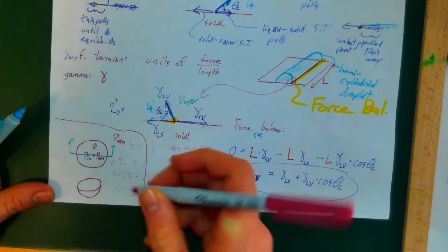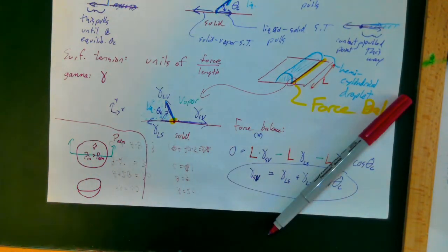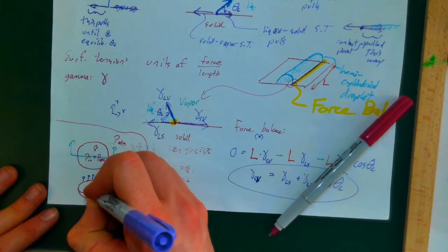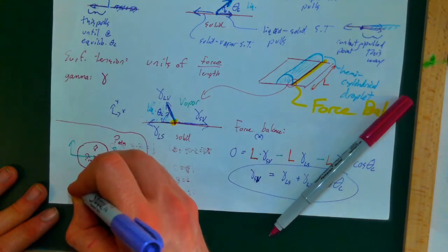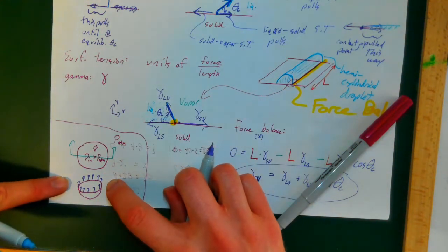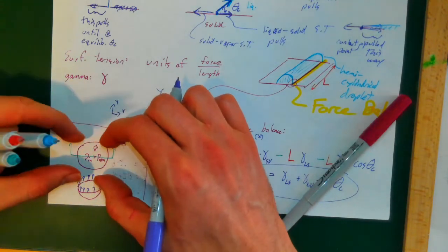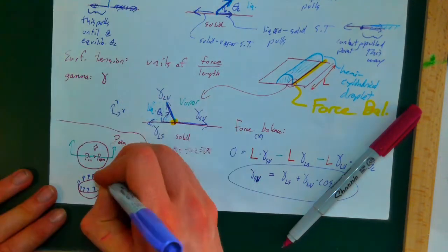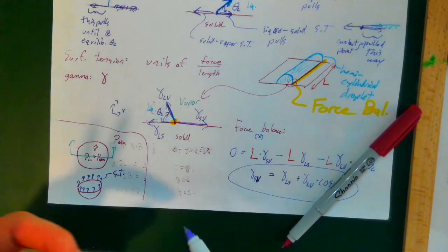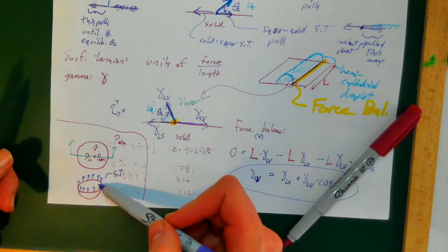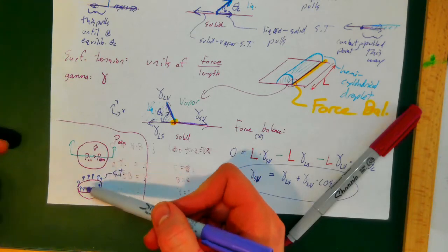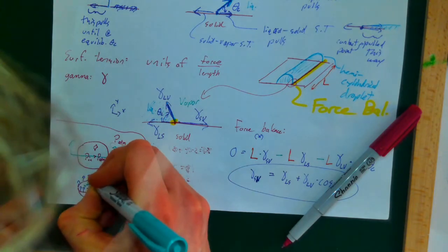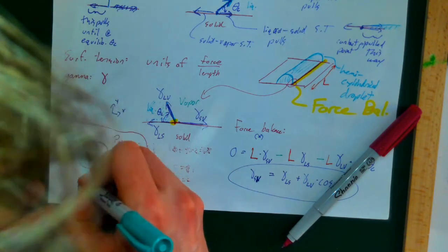imagine a hemispherical half of a bubble. The liquid vapor surface tension of this droplet is essentially pulling along the equator of this, it's basically trying to pull the two halves of that surface together. So surface tension is basically pulling like this. So what does that mean? Well, if I were to imagine, there's no net force on this bubble, right? It's not going anywhere. So what does that mean? Basically, I need pressure.